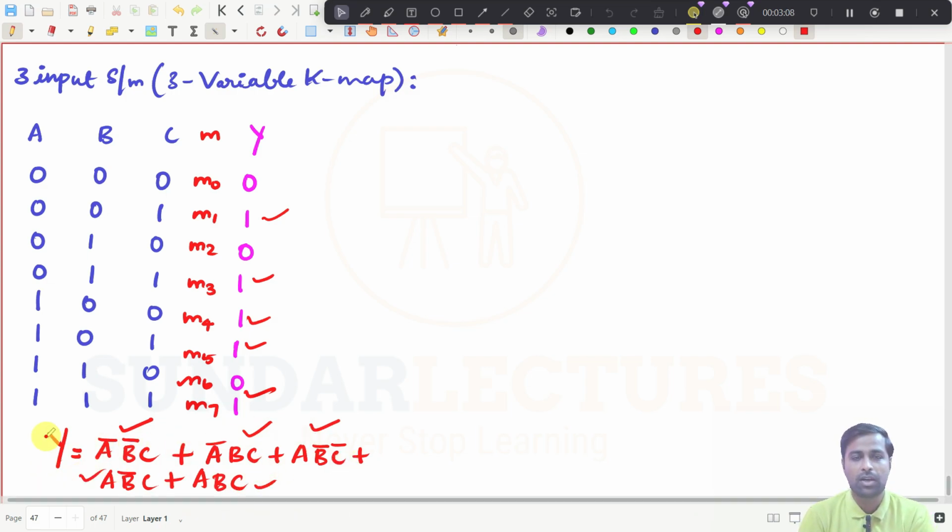That's all. So now this is the Boolean expression, and you need to simplify this expression into a shorter form. Boolean simplification, that is what we are going to do with the Karnaugh map, and there are so many basic things there. You have to see pair, quad, octet, and you need to simplify with those techniques. And we are now just seeing the basics, right? So now you see you have written it as the Boolean expression here. What is this now? It is in canonical form.